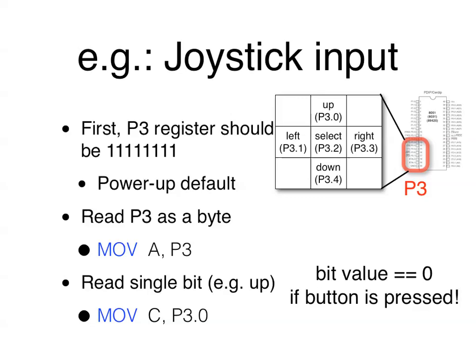By that, I mean at least all the 8051 GPIO pins I know, by default on power up, go to all ones. So it's safe to input. You need to change it only if you try to use those pins more aggressively, both as input and as output over different times. Then yes, you have to set the particular pin to 1 before you can read from it. Otherwise, think of 1 as allowing input.